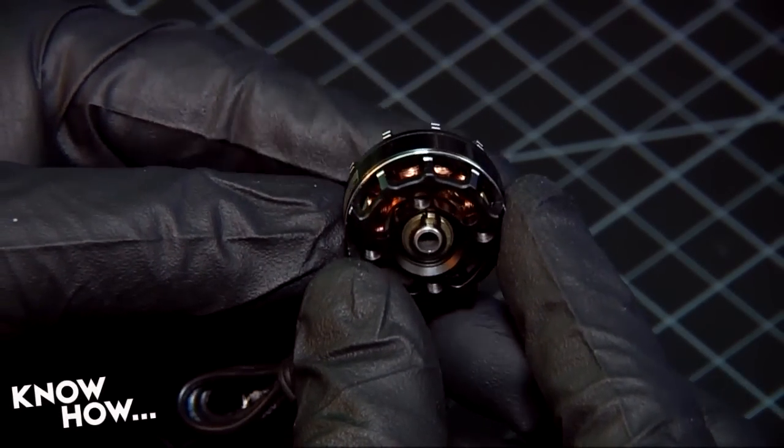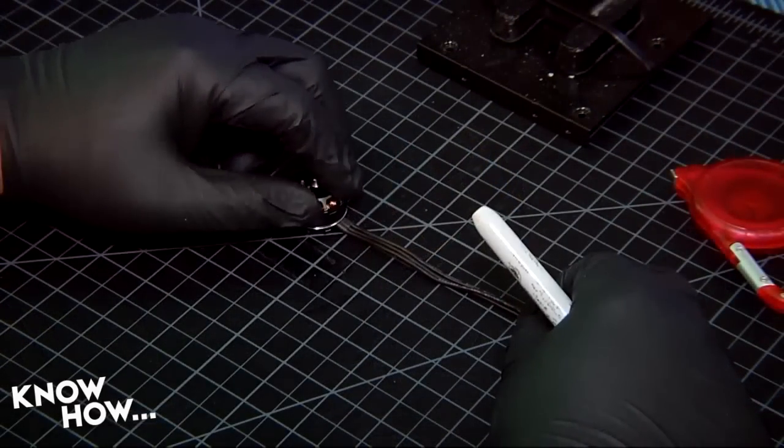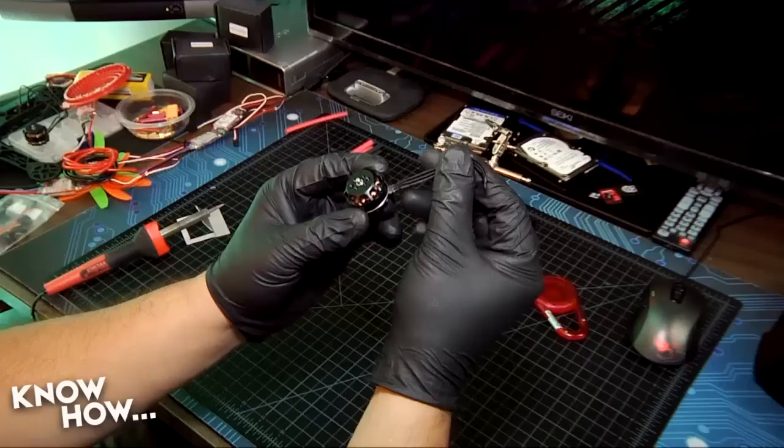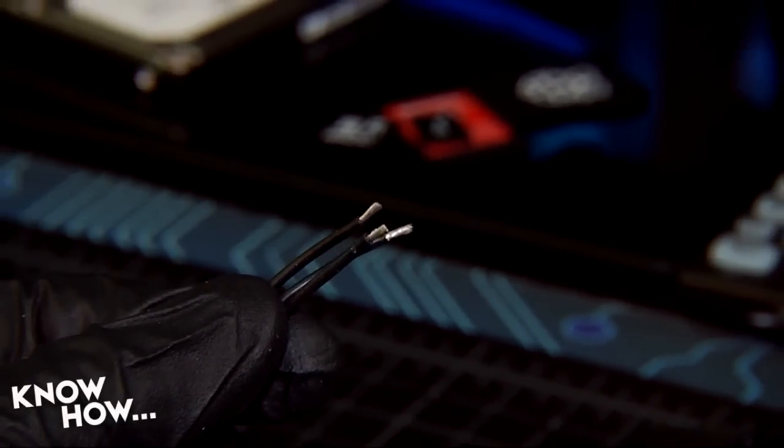We're using RTFQ 2204 series cans and 30-amp ESCs for our build. Start by cutting down your motor leads to just over 3 inches from the can, then stripping 4mm of insulation from each wire, tinning your leads.